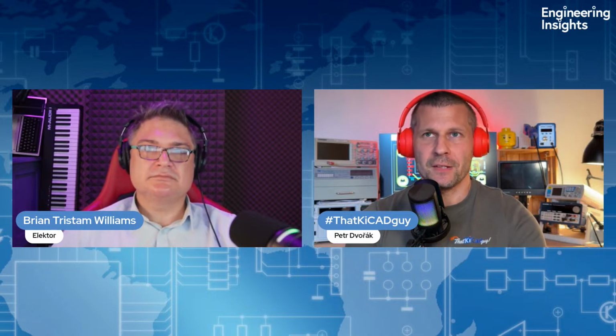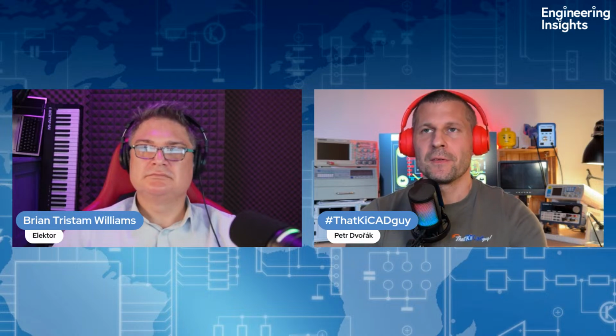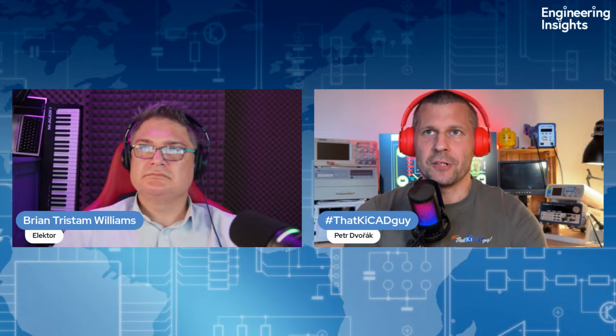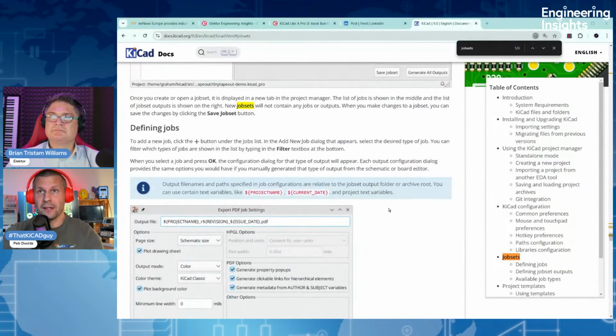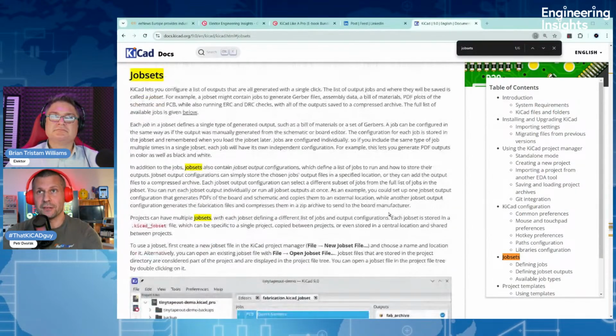The job sets is a tool or approach to tools that, for instance, we want to export manufacturing data. It means Gerbers, ODB++ in version 9, drill data, bill of material, PDF of schematics. And until version 9, we had to click on every single tool and export piece by piece. And now the job sets can be defined. You can define, for instance, 10 steps in the job set, and by single click, you call the job set and everything is exported automatically.